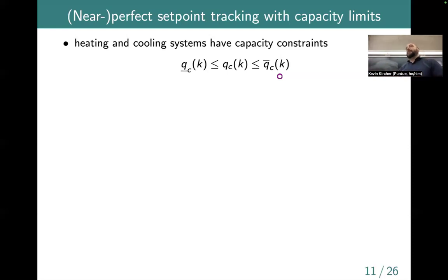I think it's more antiquated buildings like this one, a little older, that typically would have this kind of binary operation thing. And I'm not exactly sure why. I think part of it is to save energy. It seems a little wasteful to be air conditioning over here and heating over there. Yeah, it's a good question. Sometimes you have only one piece of equipment, and you might have an air source heat pump, one piece of equipment that provides both heating and cooling. And you might have to physically trip a switch or something in order to flip it. So there, again, this model of exclusion between heating and cooling makes sense. Good question. Any others?